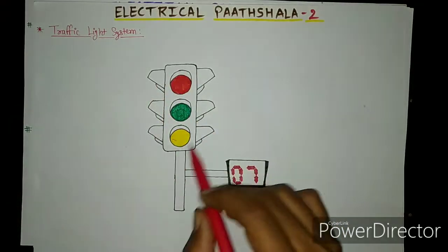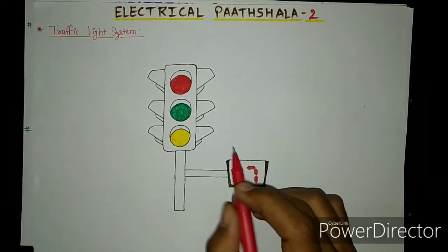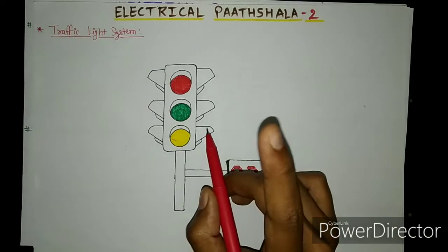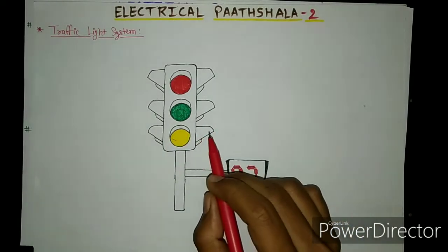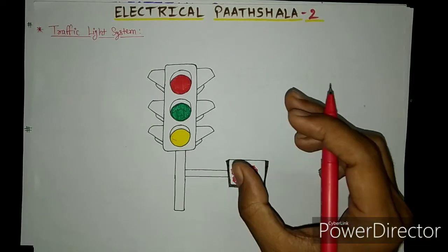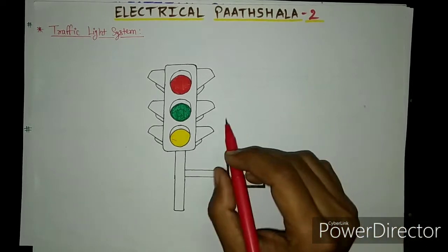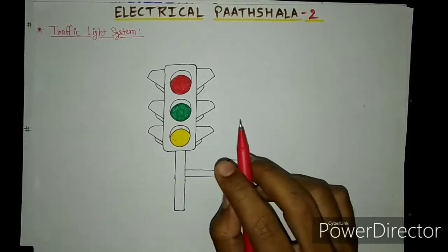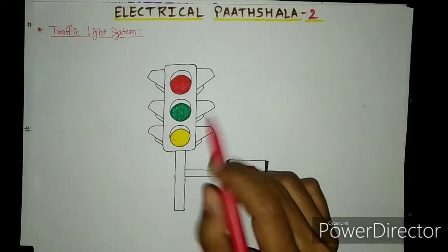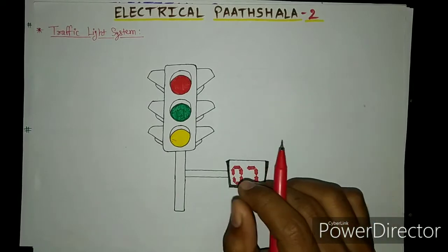Now this is an open loop control system, and you know that for an open loop control system, once the input is given, it should not be changed, and there should be no disturbance in the forward path. If these two conditions are satisfied, then for a given input you will obtain the desired output. But if you change the input, then the output of the system will also change accordingly.